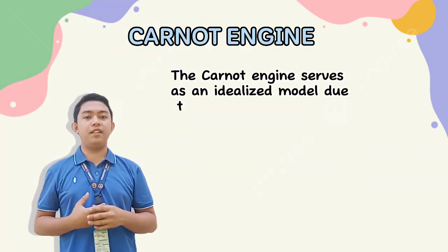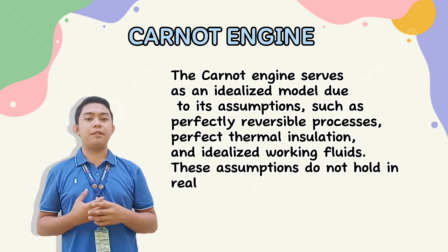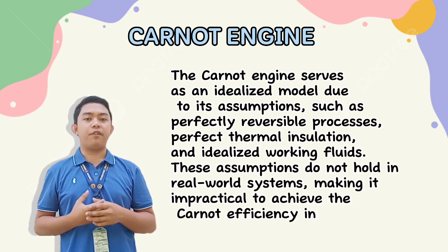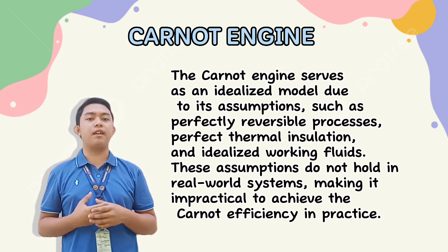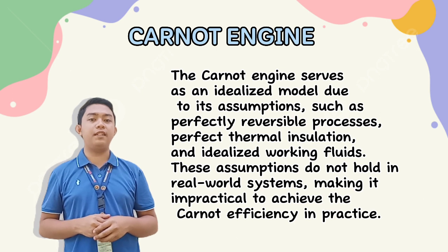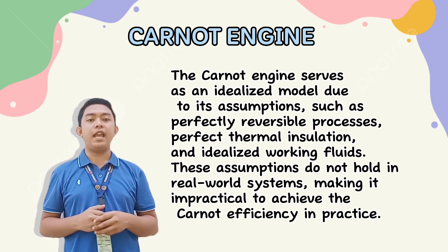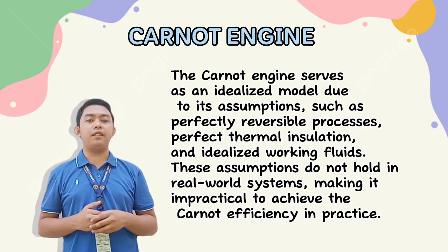The Carnot engine serves as an idealized model due to its assumptions, such as perfectly reversible processes, perfect thermal insulation, and idealized working fluids. These assumptions do not hold in real-world systems, making it impractical to achieve the Carnot efficiency in practice. Additionally, the Carnot engine does not consider factors like friction, heat loss, and practical constraints, which further limits its applicability to real-world engines.